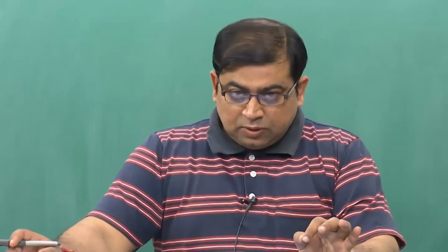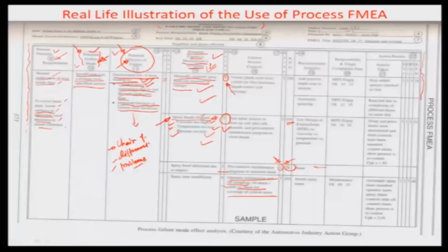So here the assembly engineering, or the process engineer, decided to use a DOE, or design of experiments, scheme where you could optimize the various parameters related to temperature, viscosity and pressure. An optimization was carried out based on viscosity versus temperature versus pressure, and a solution was provided as to what would be the ideal ranges of these different values. Manufacturing engineering again was given a target of implementing this by a certain date, which they did. So the temperature and pressure limits were determined and limit controls were installed.